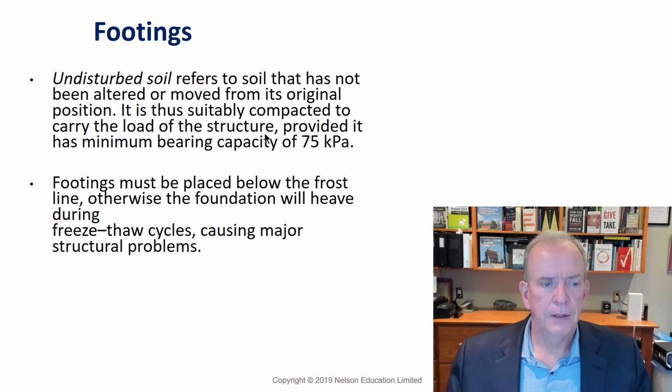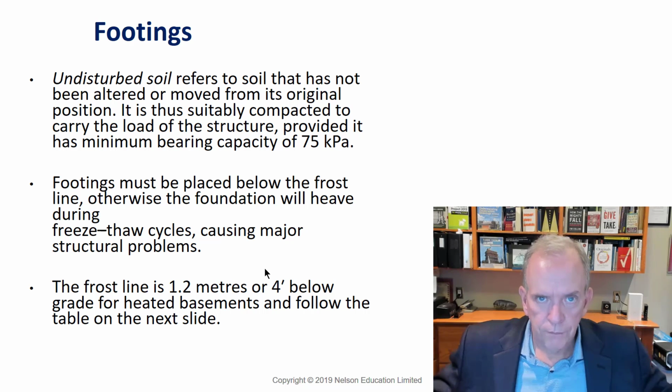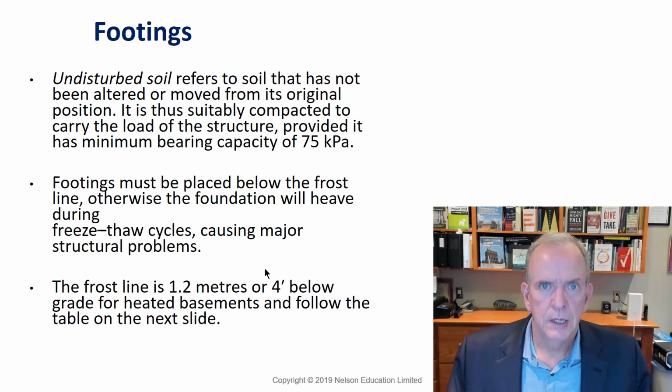So the frost line, for us, is 4 feet or 1.2 meters below grade. So we have to excavate at least 4 feet below grade. That is the requirement we need to construct by. Because if we don't, frost in our areas in Canada, if it's a heated foundation, we assume some of the heat will get out of the foundation, so it won't freeze around the base of the foundation. But we have to get at least below 4 feet.